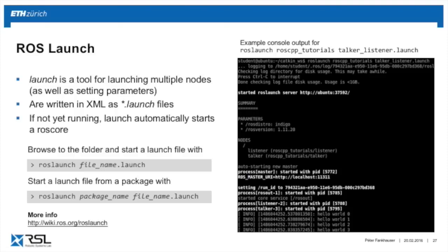Also, as a side note, if not yet running a ROS master somewhere, roslaunch will automatically run this for you. It means you can go into a console, type in roslaunch and the launch file that you need, and it will boot up everything that you need.